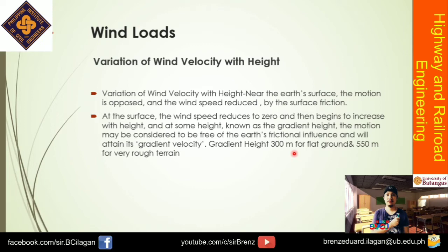With height, at some height known as the gradient height, the motion may be considered to be free of the Earth's frictional influence and will attain its gradient velocity. The gradient height is 300 meters for flat ground and 550 meters for very rough terrain.